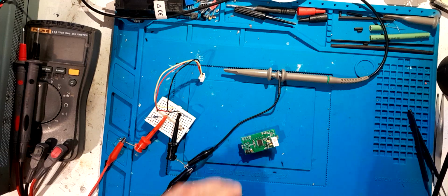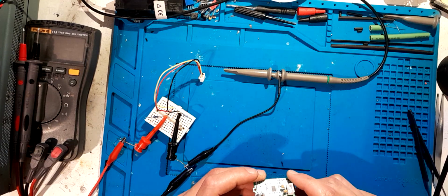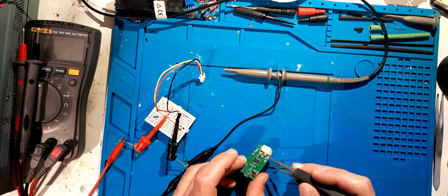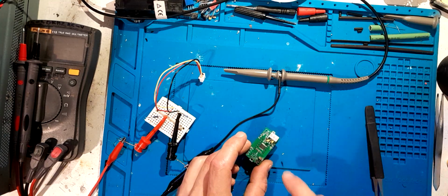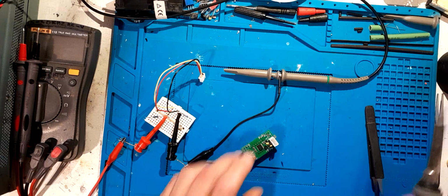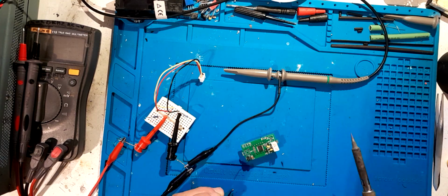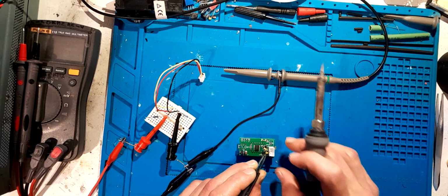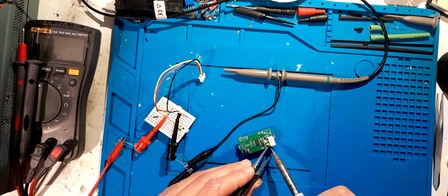Alright. So what happens if I just literally tack it across our positive rail and our ground point there, effectively giving a 1 microfarad monolithic cap and a 10 microfarad ceramic to bypass the power rail coming in. I'm just going to give it a shot. Why not?